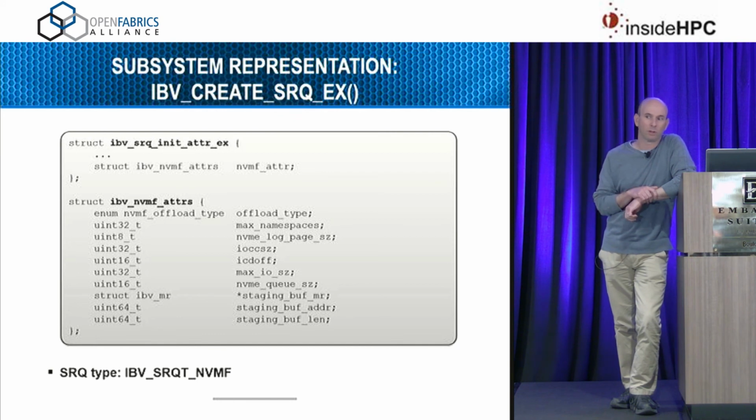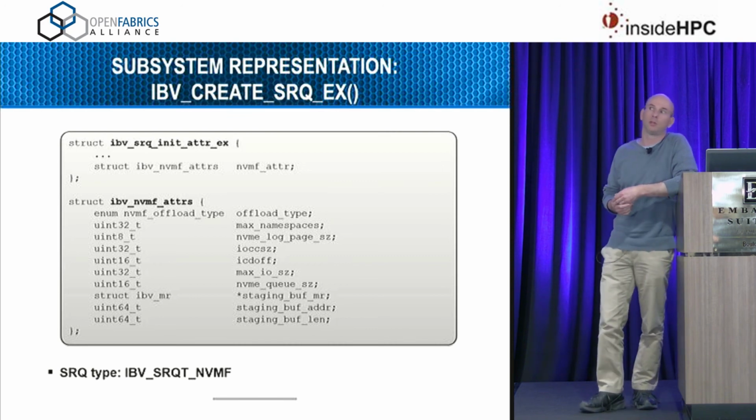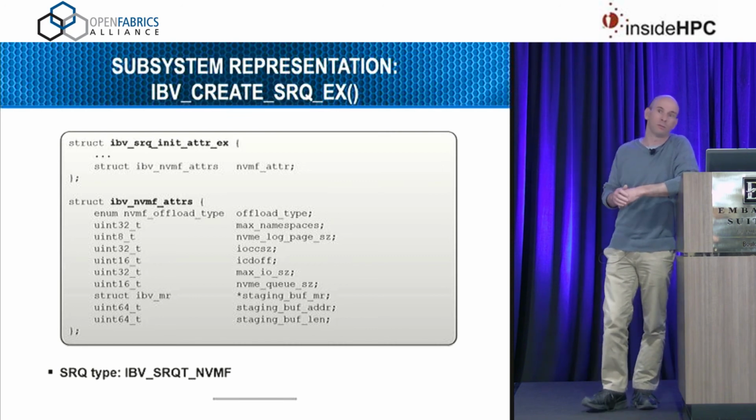Okay, so first of all, in terms of the offload itself, nothing here is proprietary. When you look at how an NVMe frontend needs to process an NVMe request, what you need to do is completely covered by the standards. So on that front, nothing here is implementation specific. In terms of why you need it through verbs, it's because we don't want to do everything in hardware. We want most of the management to remain in software, possibly, if we're going to push it in the kernel, of course, we want to reuse the existing NVMe-oF target to manage all that.